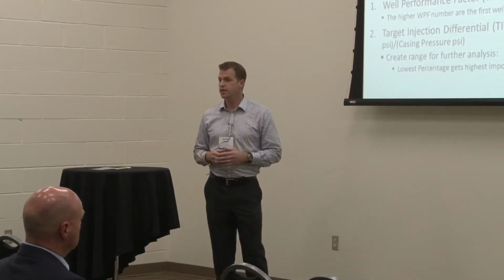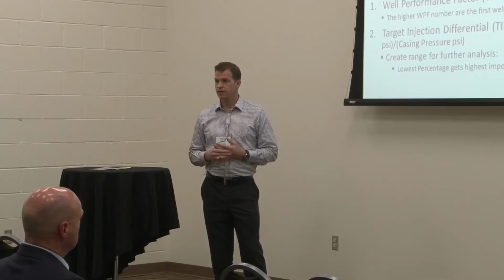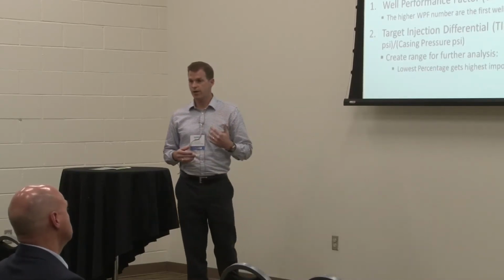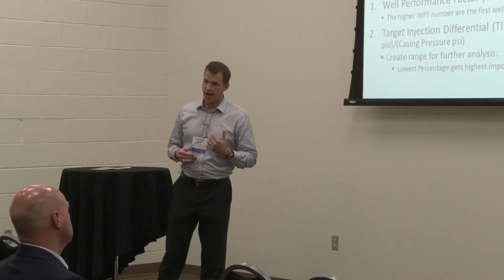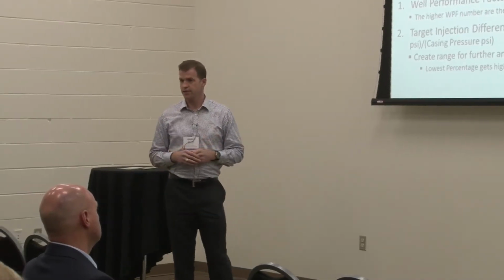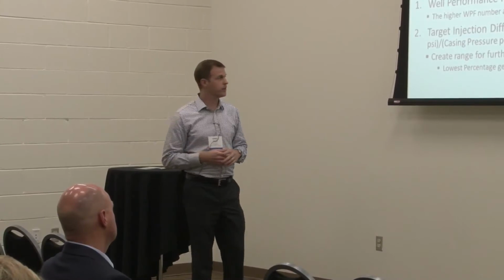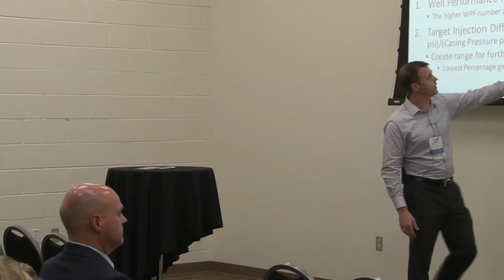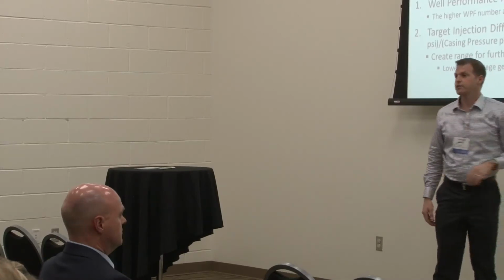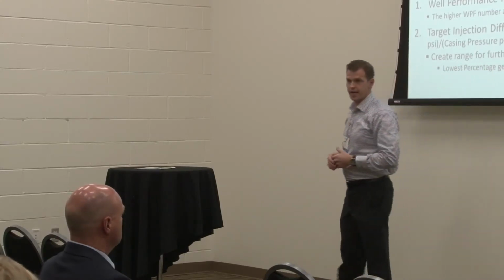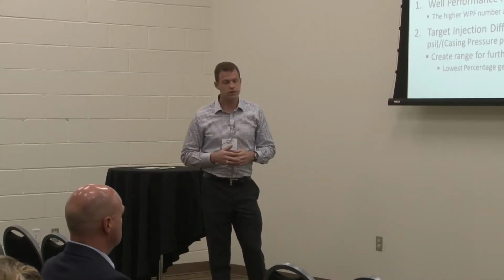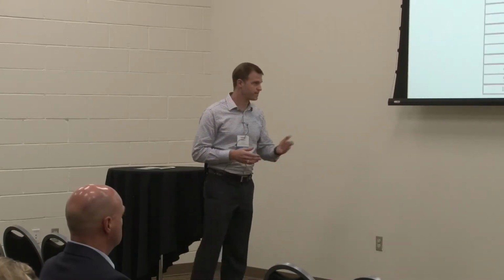be flow lines or high pressure separators, ways to improve our surface facilities that will show back in production increases and lower compressor operation. Because if we can, with our injection differential, if we can lower our casing pressure and still maintain production, we can lower our horsepower, we can lower our rental costs with our compressors.